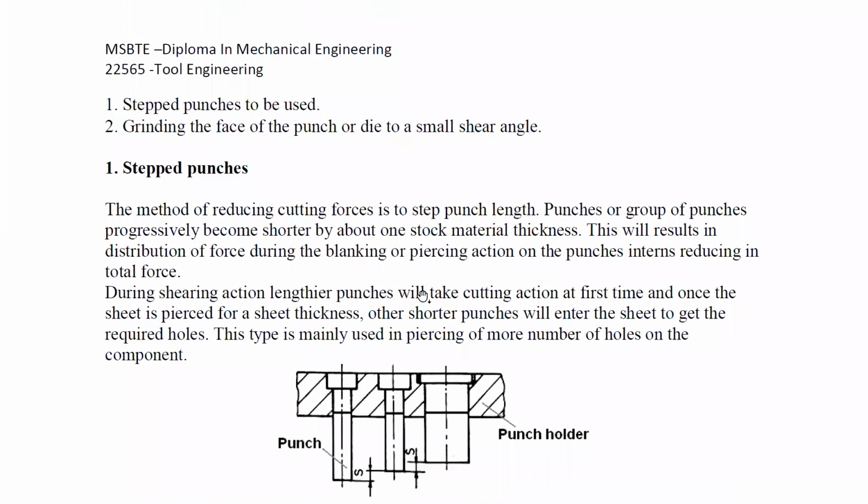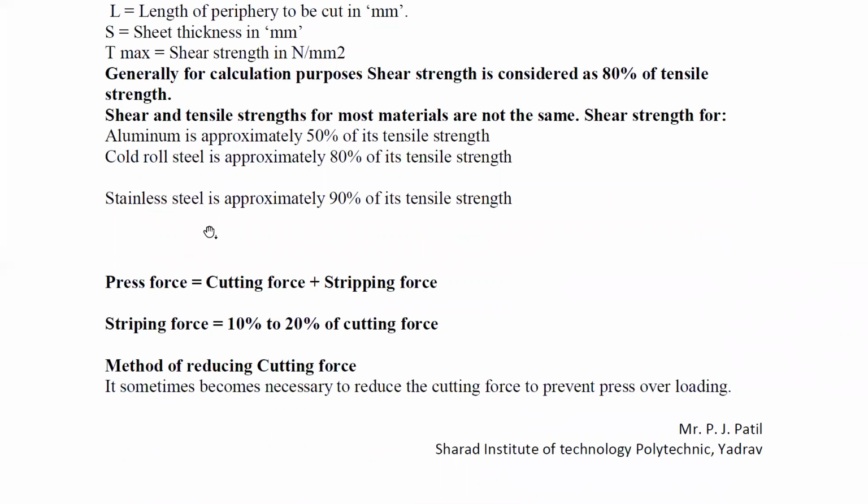So again, press force. What is this press force? Press force is the summation of cutting force and stripping force. Cutting force is what we have calculated above, the force required to cut the material from its stock. And what is stripping force?